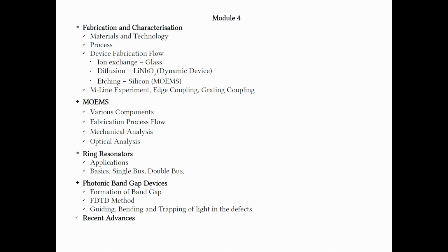recent development that we have taken up is called the ring resonators. In order to reduce the chip utilization, we thought ring resonators are important components, but in terms of the functionality also they have very important properties. In particular, like the gratings, they have frequency dependence. So the resonant frequency is a very sensitive function of the radius, then the bus waveguide, then the gap between the bus waveguide and the ring resonator, and so on and so forth. So ring resonators, we have found them to have many applications.